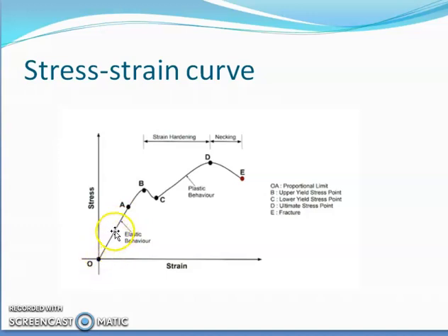So you can observe in this curve, at the very start of the test, what happens? The material capacity increases as stress is directly proportional to strain. At a certain point, what happens? The material capacity reduces. But after that, what happens? The material capacity increases, right? On the further application of the load, material capacity increases. So this property is called strain hardening.